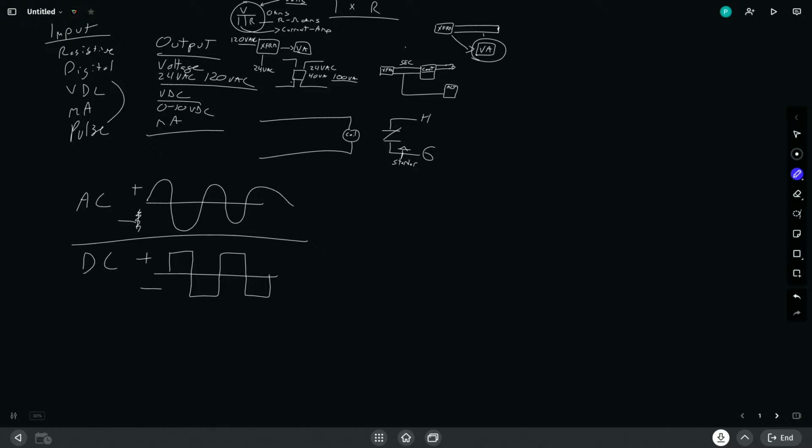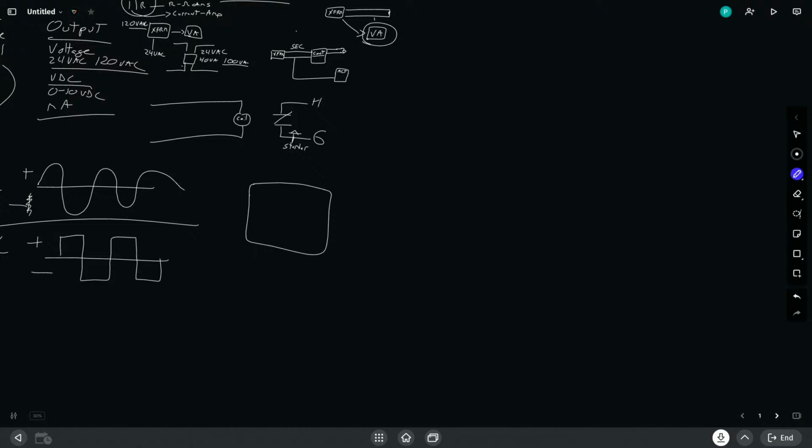So continuing right along, the last thing that I will leave you with here in regards to these electrical concepts is just a little tidbit in regards to controllers and amperage. On inputs and outputs, controllers have amperage ratings. And remember, amperage is heat, amperage is current. And if we have too much amperage, we can damage the internal components of our controllers. So we need to be cognizant of the amperage ratings of our inputs and outputs when we attach devices to them on the controller so that we don't damage the controller.